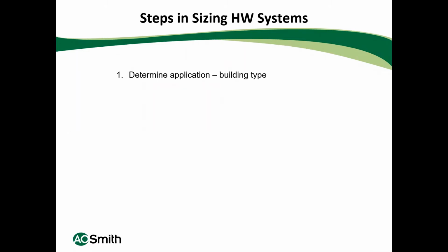The low peak would be a building that was mainly seniors, so maybe a seniors building would be a 3-hour recovery. If you have a mix of people, like working people, students, and seniors, that would be a medium peak. And if it was all students, it would be a high peak. So we need to determine that.